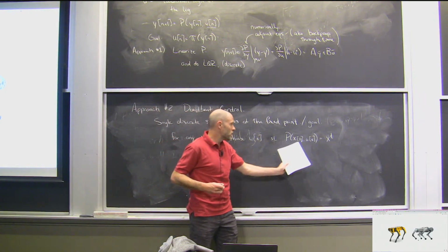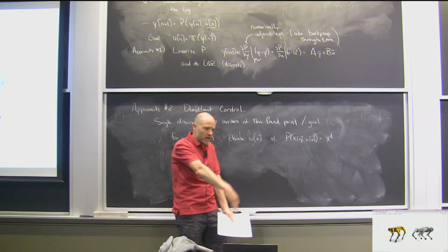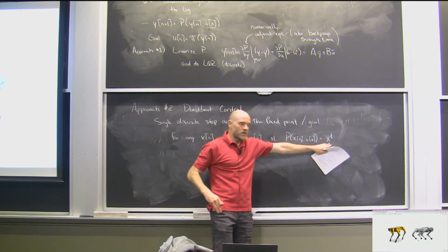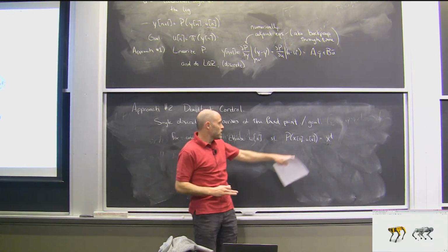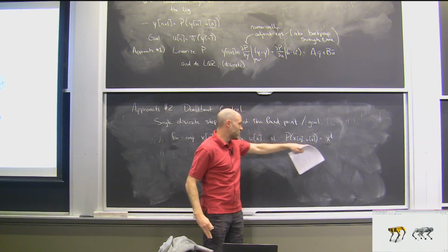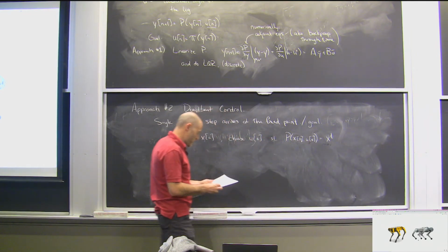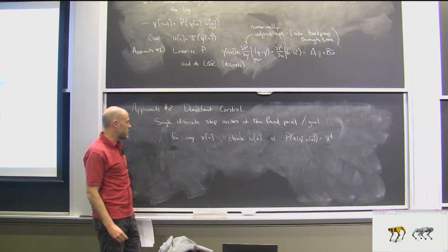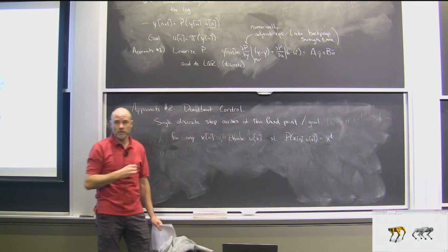So that for any x desired, in the domain where the energy is fixed and your leg is not horizontal, it's not completely invertible for any possible x desireds. There's some x desireds that you don't have enough energy to achieve, but in some important operating regime, this map is effectively invertible. And that is that you can give me x desired and x0 and I'll solve for the u that will achieve it, okay? And that's an extremely cool observation that is a little specific to this, but this notion that you can achieve deadbeat control for discrete time systems is important.